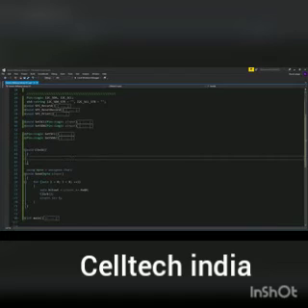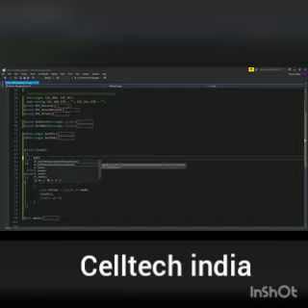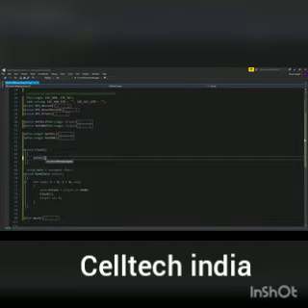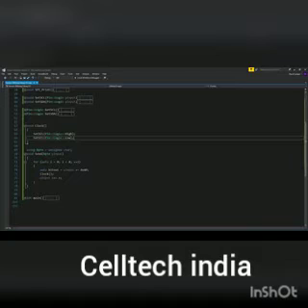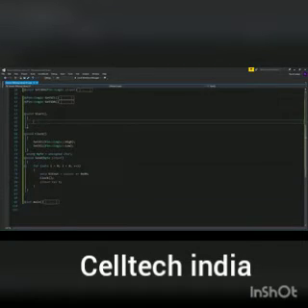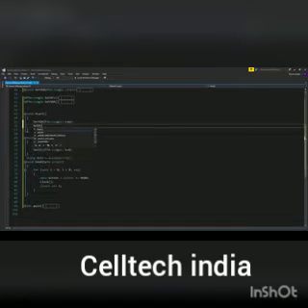Okay, in the send function, we're just going to store it temporarily. We're going to mask out that top bit, and we're going to store the temporary and probably clock it out. Clocking out is the rising and falling edge, so let's write that. Okay, so a rising edge is setting it high, then a falling edge is setting it low again.